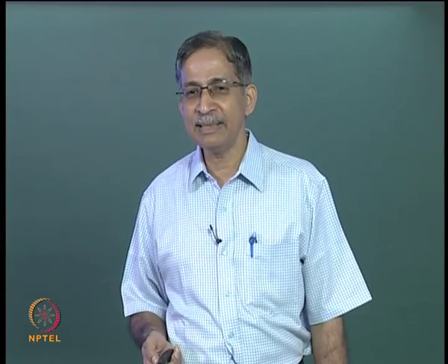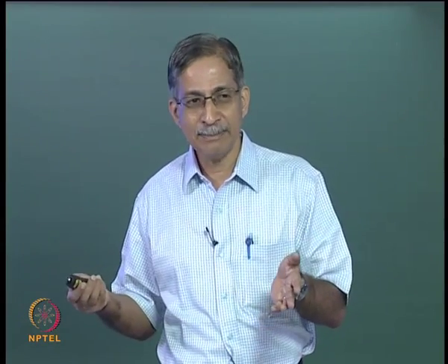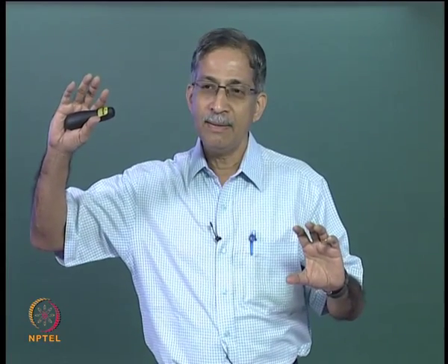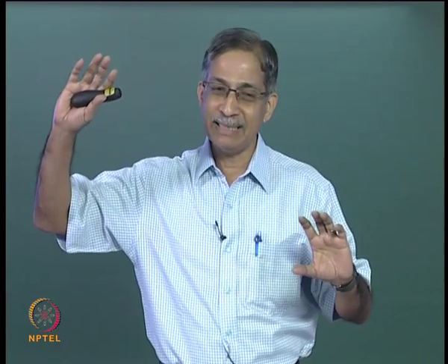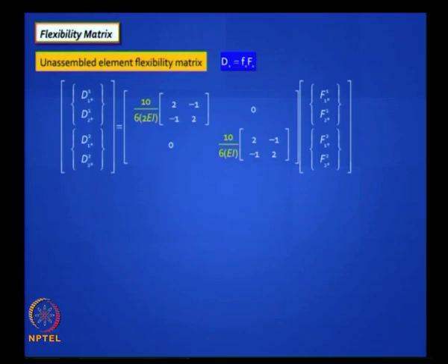So the element flexibility matrix, what is the matrix for a prismatic element? Just so that your memory is okay, L by 3EI at the diagonal and minus L by 6EI off diagonal, that is it. So you do that, you can do it in one shot, you have got the F star matrix, is it clear? Just put the correct L, which is 10 meters for both the elements, and the EI is 2EI for the first element and just EI for the second element, and the off diagonal elements are 0, are null, is it clear? Very easy to do.